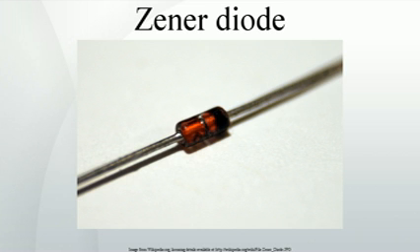The accumulation of the trapped charges can then cause Zener walkout, a corresponding change of the Zener voltage of the junction. The same effect can be achieved by radiation damage.